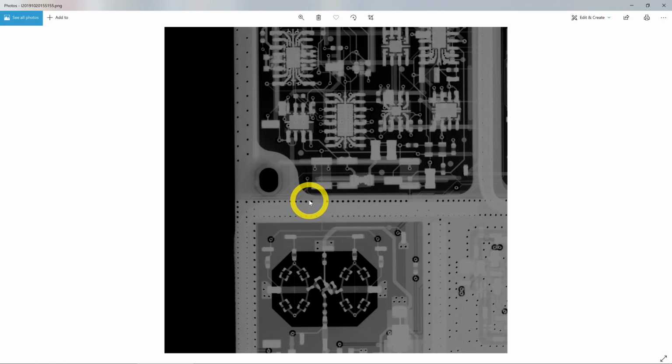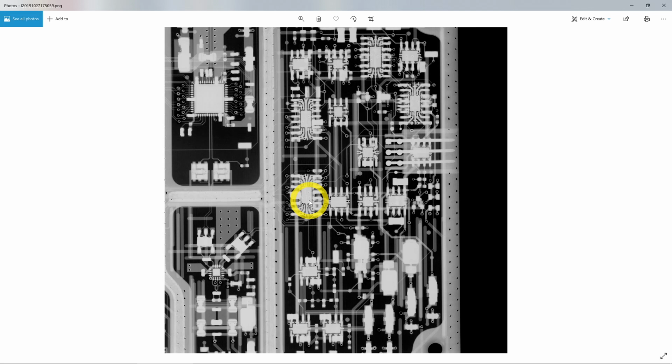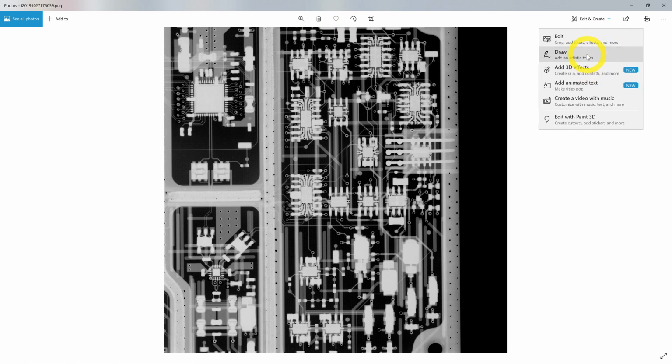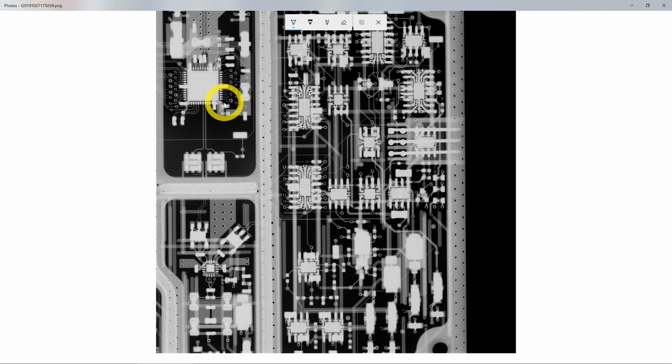At the same time, what else did I take a picture of? Let's see, this one is interesting. So here is the mystery IC that I keep talking about. It's a programmable divider. That's this one. So we measured the input to it. I already put the probe here. We saw that it sweeps nicely. I also put the probe at the output of these filters, and we looked at that, and that was the 50 megahertz signal coming out.